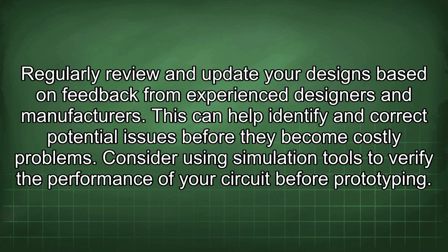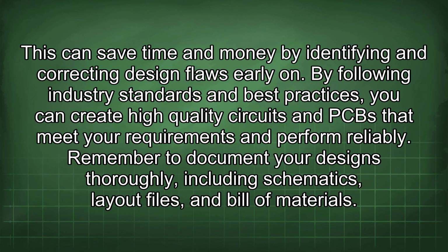This can help identify and correct potential issues before they become costly problems. Consider using simulation tools to verify the performance of your circuit before prototyping. This can save time and money by identifying and correcting design flaws early on. By following industry standards and best practices, you can create high-quality circuits and PCB that meet your requirements and perform reliably. Remember to document your designs thoroughly, including schematics, layout files, and bill of materials.